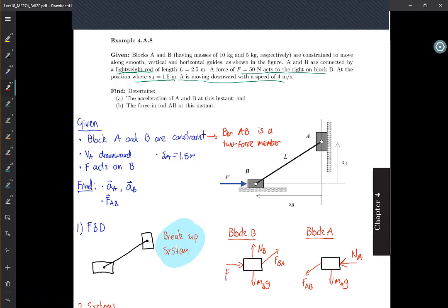Exactly. Lightweight rods can have negative or positive forces. They can sustain tension and compression, right? I can compress this pen, but if I take a cable and I compress it, it just bends. It doesn't carry compression, all right? So this is helping you to solve the problem that is due today. Tension can only be positive on cables, essentially. That's a condition that you need.